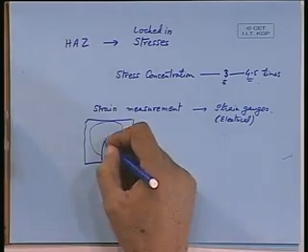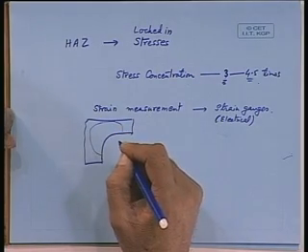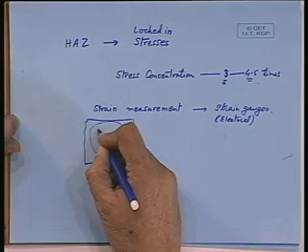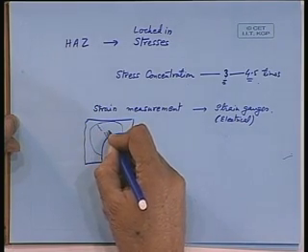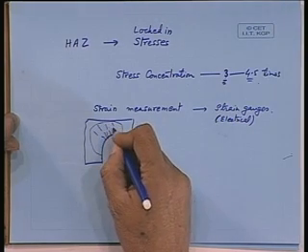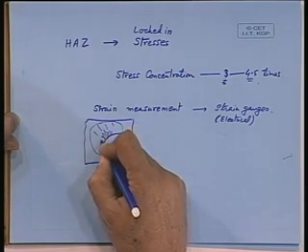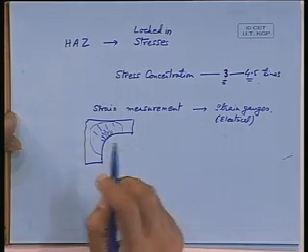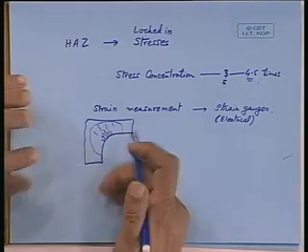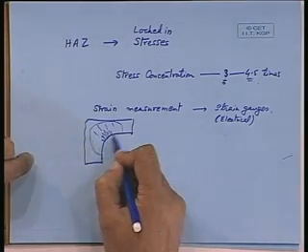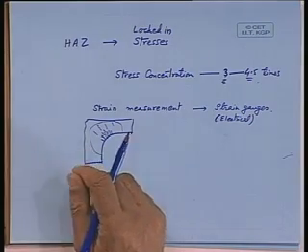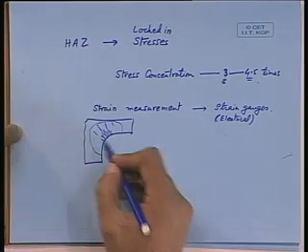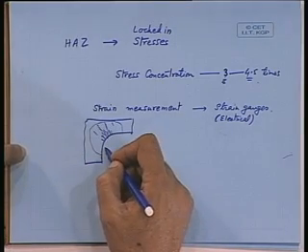So, when there is a stress concentration, the brittle material will have a crack, and knowing the amount of crack in a particular zone, one can find out how much stress is concentrated here. If you have a large number of cracks in this zone, then you can say that the stress is concentrated. If some cracks are there, it may be a continuous crack also, who knows. So then you can say that the stresses are less in this region, more in this region.